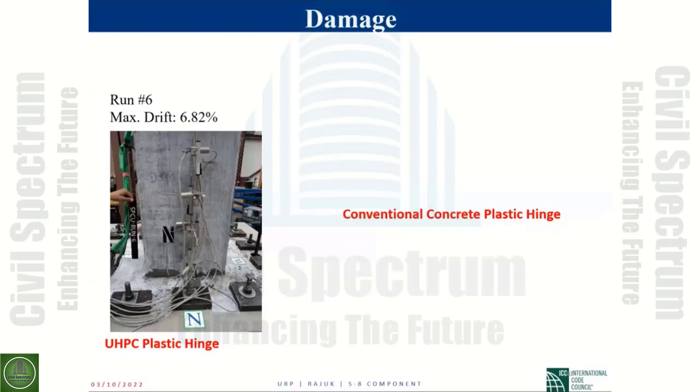So after a strong earthquake, if you go to the bridge site, and this is what you see, considering that there is no permanent displacement, you would say, yeah, this bridge can be left open to traffic. You don't have to shut it down to ambulances, fire trucks, and all the emergency response vehicles. There's some damage at the bottom of the column, but that's minor and that's repairable.